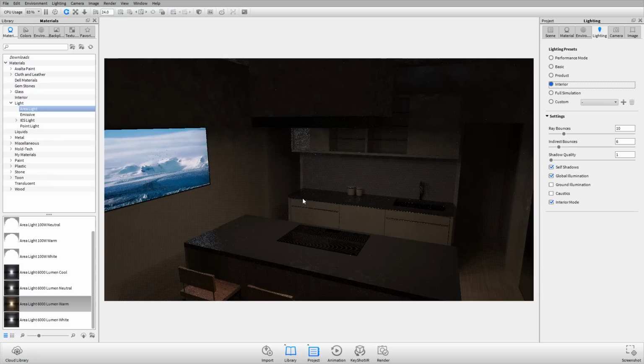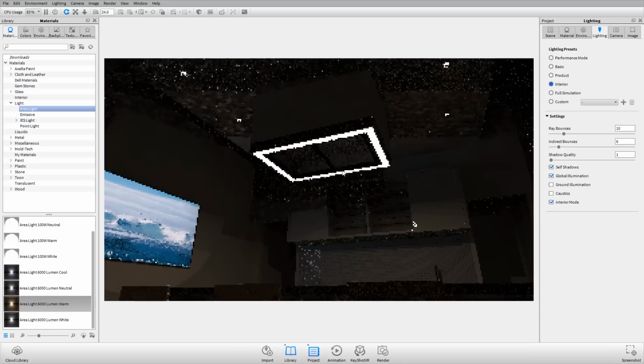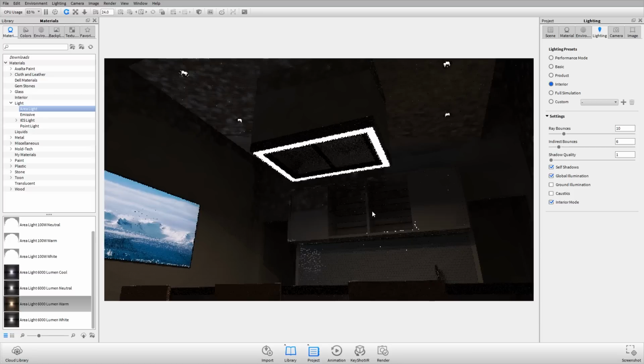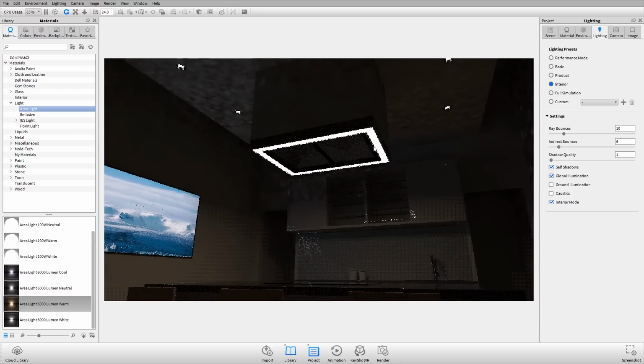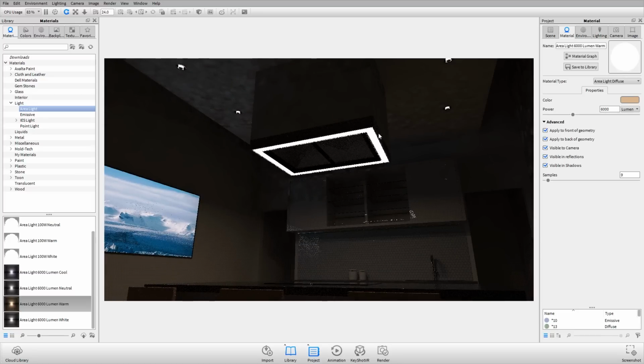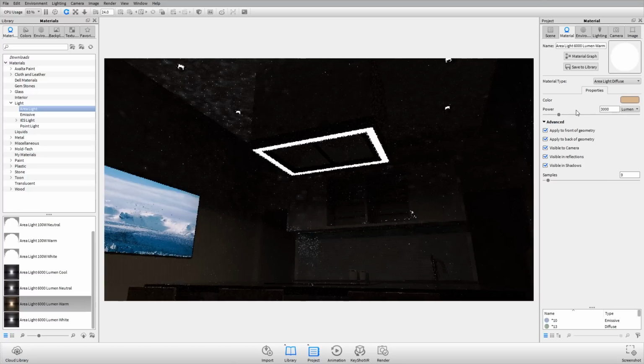And if you notice, almost in the same amount of time, we got some spots, but they're going to disappear. And they're going to be constantly being squished by our noise suppression algorithms, right? But now we have our light shining down, and it's providing the light in the scene, or most of it. So that material is an area light. I might drop that down and make it a little less bright if it's just kind of the light for the hood. I don't necessarily need it to be as bright.